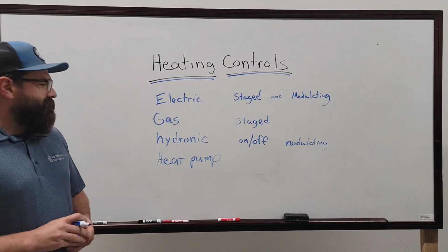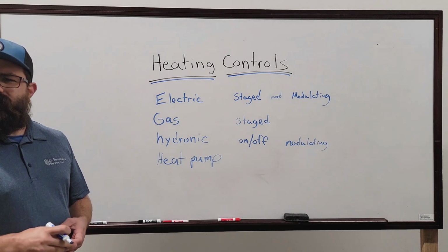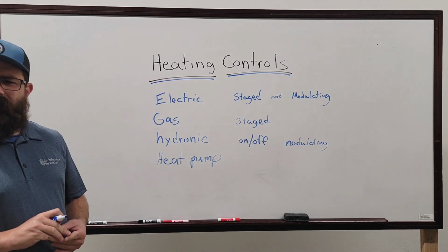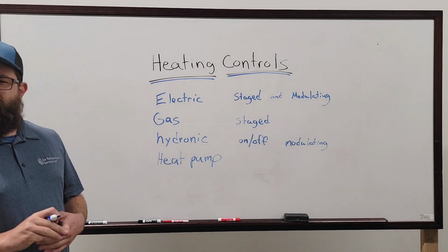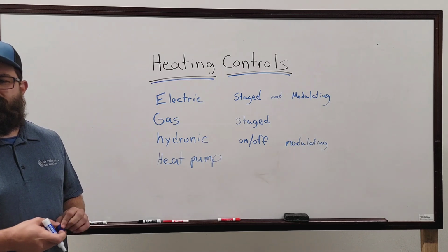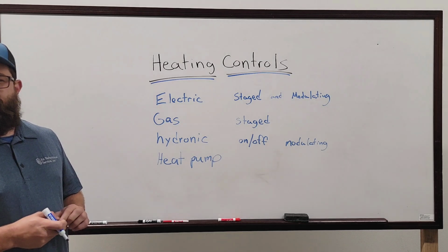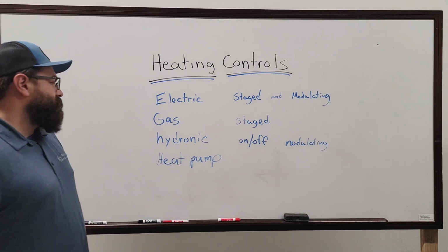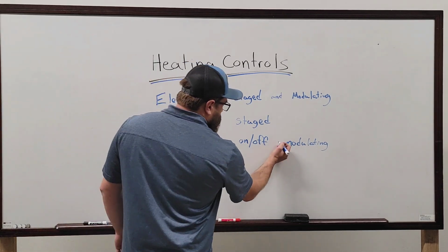I don't think I've ever had one that's got multiple hot water valves. That would be a weird scenario. I guess you could consider a multi-zone unit, but each one of those is independently controlling a space, so you're still talking about individual. So it's going to be on, off, or modulating at that point.